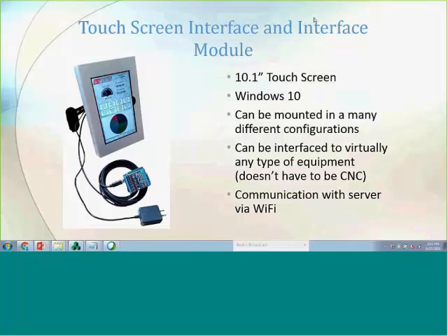One additional comment, because somebody had mentioned something about the OS specifically, and this is on the InduSoft side of things. People ask, well, why didn't you use something like Windows 10 embedded or the Windows embedded operating systems? That's really more of a constraint on the InduSoft side, that when you use our embedded images, the support for third-party .NET controls is not there. So once Cam had these third-party .NET controls that he wanted to embed into his application, that made the decision easy for him to go with the full Windows 10 OS. Yeah, exactly.